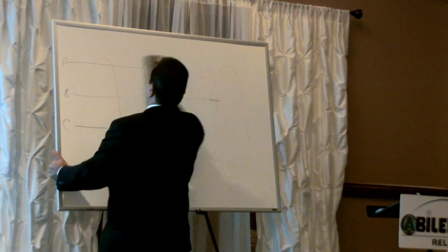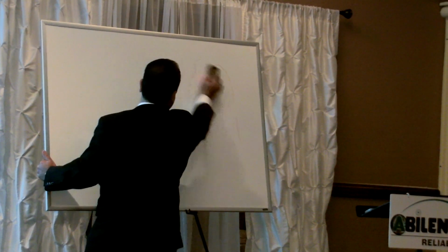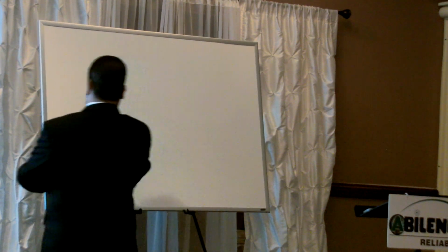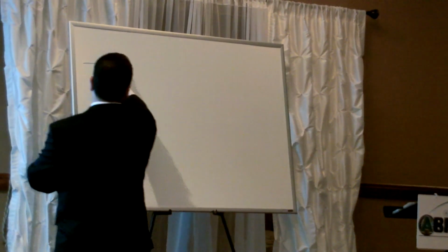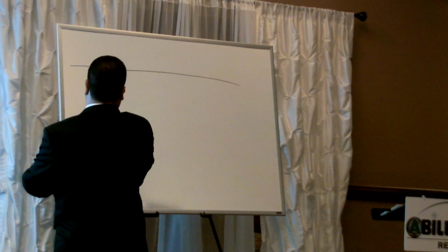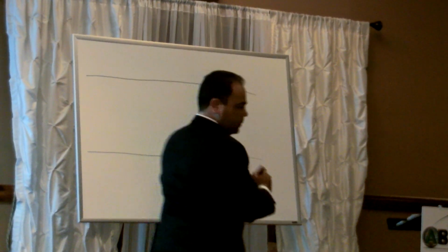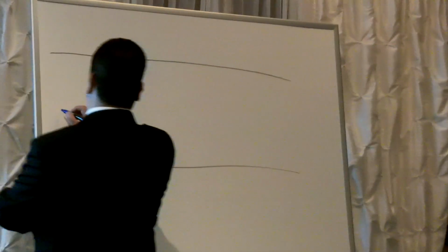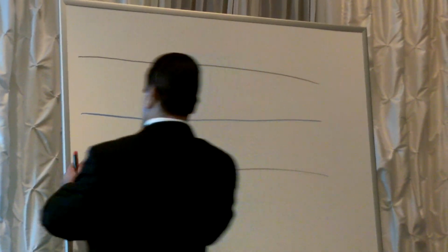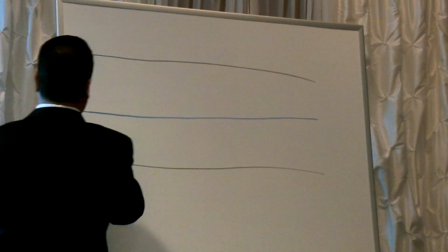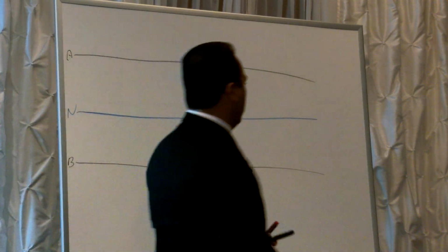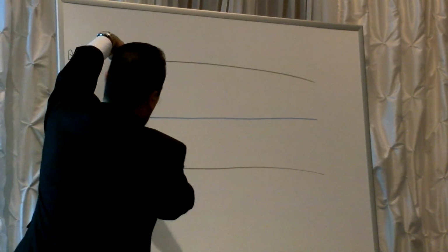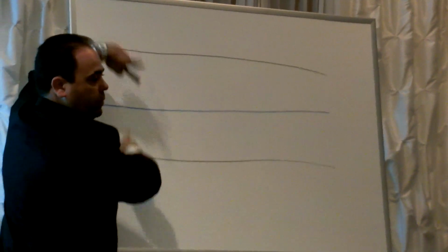Now, seeing that you brought that up, on a single phase, 208, this is neutral, that's A, and that's B. Single phase 208, because like we saw on a slide before, two phase legs, I'll get 208 in between the two.